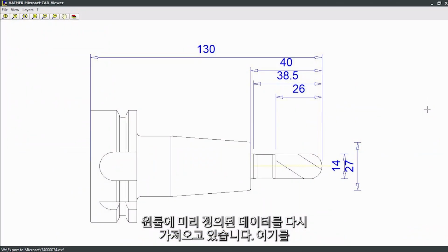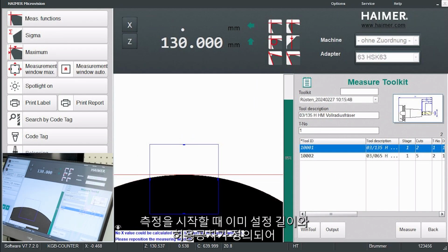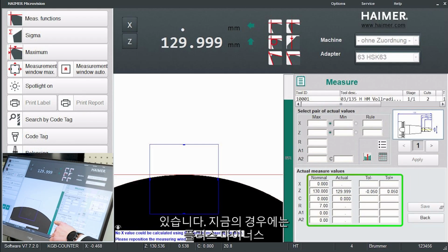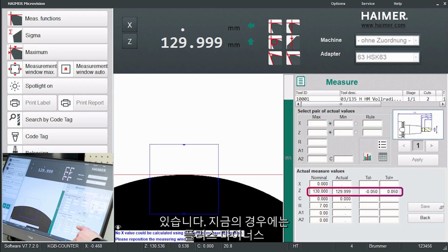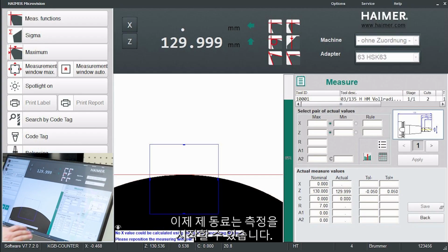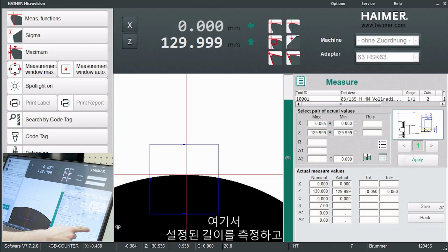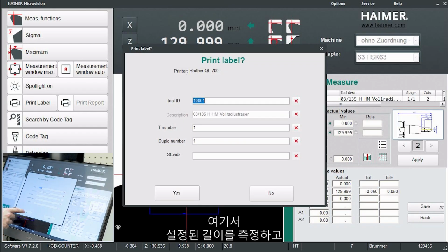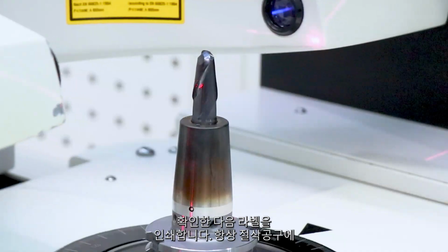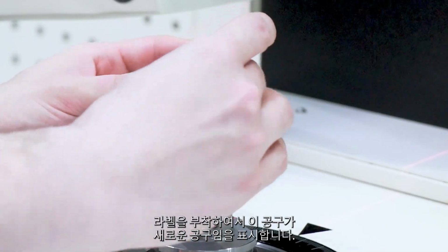When I double click here, I also have again the 2D drawing, which is sent via WinTool. And when I start the measurement, there is also already predefined what is the nominal Z length and what is the tolerance, in this case, plus minus 0.05 of a millimeter. And now my colleague can start doing the measurement. In this case, he's applying the Z length, confirming it, and then we are printing out the label, because we always want to have the label around the cutting tool signalizing it's a brand new tool.